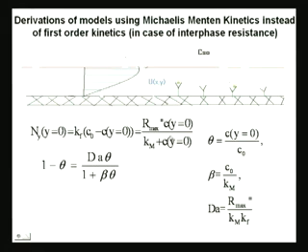Then R max, so divide both sides again by k f k m. You will get the Damkohler number on the numerator times theta, over 1 plus beta times theta. The k m goes from the denominator because you have divided by it. Beta comes because of C naught and k m, since you have divided both sides by k m, and theta comes because of C over C naught. Is that fine, or do you not want me to go through that step? Fine, right. Now it is pretty straightforward. This is a quadratic equation, and I am going to solve it directly. So, why don't you put the equation in that form and quickly get the solution.